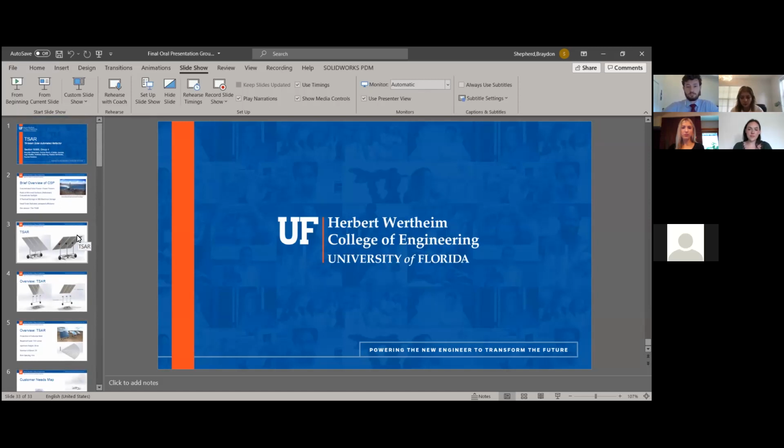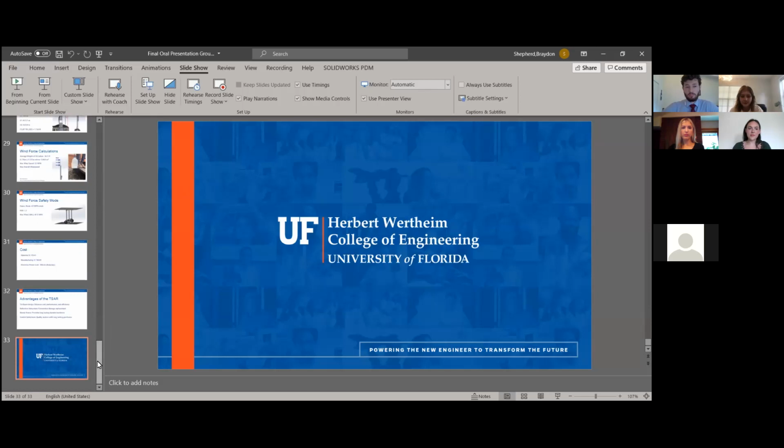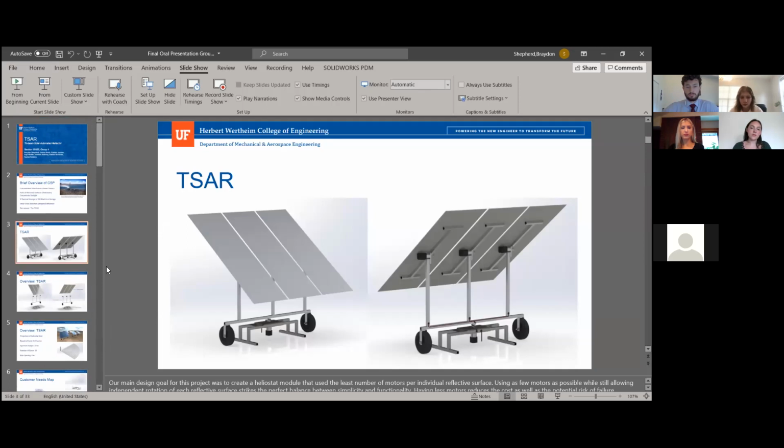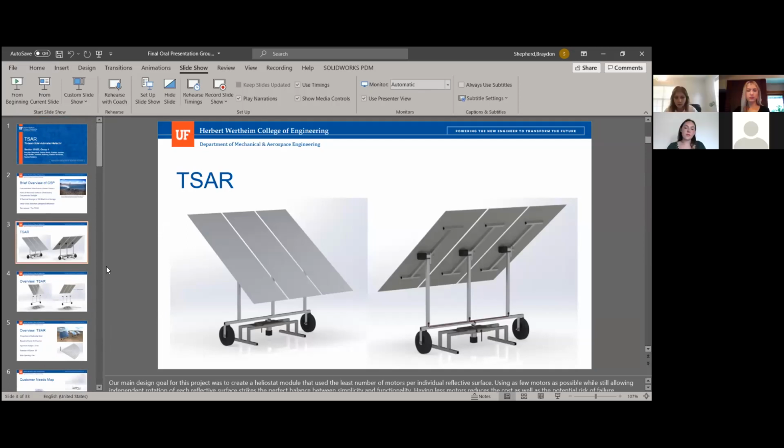Hey guys, this is Tom Singer from Northrop Grumman. I know we talked a little bit during your poster session, and I'd asked about the stability of the system, where you have the wheels oriented in parallel to what winds up being a sail in the wind. Is there any thought about iterating that design and adjusting that moving forward? Because right now you've got a lot of wind force impinging a good distance up, and nothing really providing stability to that except for the axis of that vertical motor right there. And that's a significant concern for me.